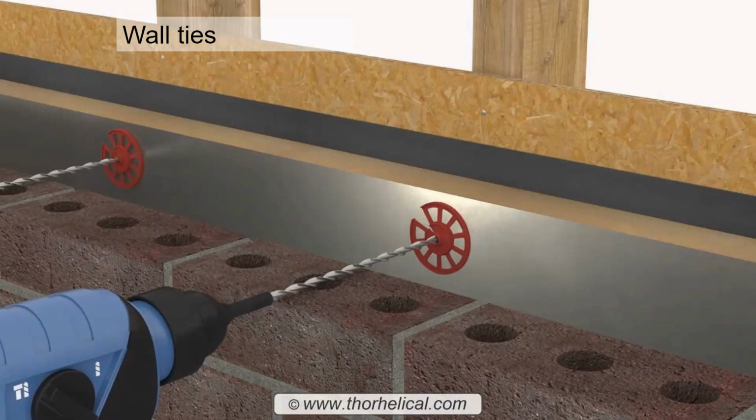And usually what wall ties are, they are either a helical screw that's fixed back into the sheathing and the stud behind. So that will actually go right the way back into here and probably fixed into the structure behind. That's the stud away up here. And in this case, it's got insulation in the cavity, and this round thing is a retaining clip.